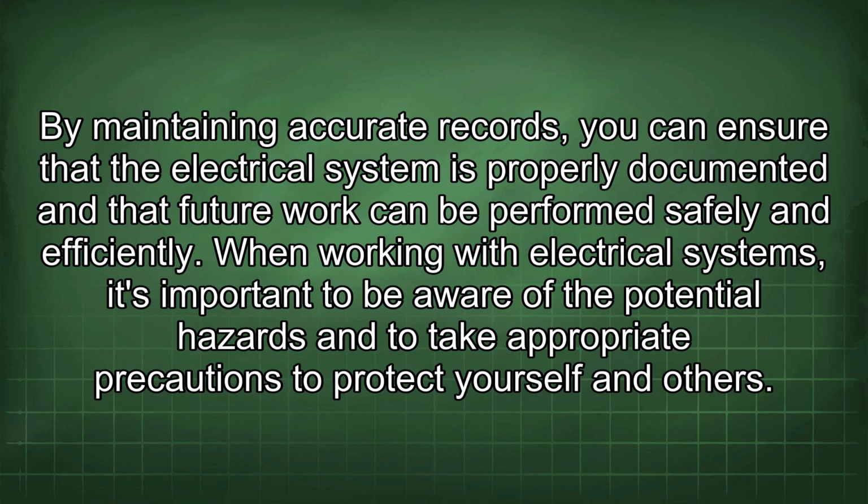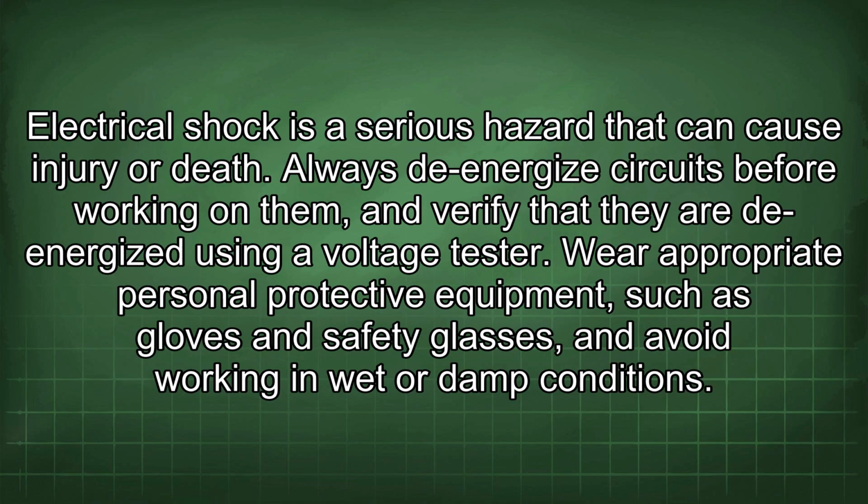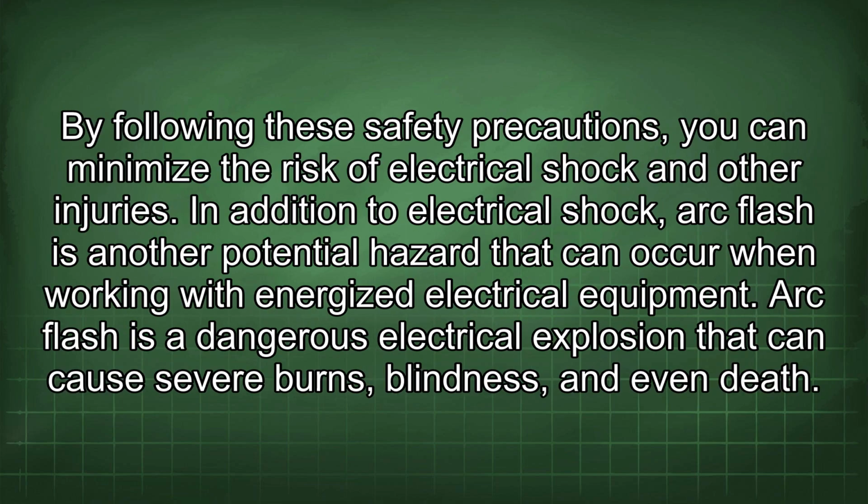When working with electrical systems, it's important to be aware of the potential hazards and to take appropriate precautions to protect yourself and others. Electrical shock is a serious hazard that can cause injury or death. Always de-energize circuits before working on them, and verify that they are de-energized using a voltage tester. Wear appropriate personal protective equipment such as gloves and safety glasses, and avoid working in wet or damp conditions. By following these safety precautions, you can minimize the risk of electrical shock and other injuries.